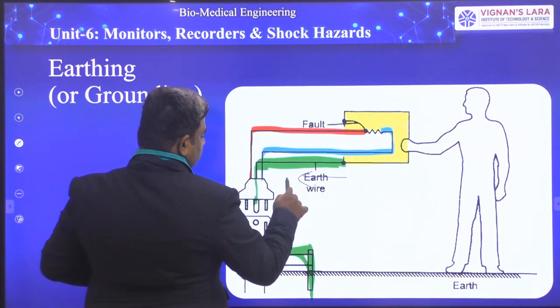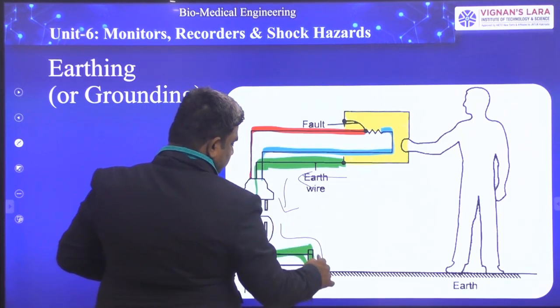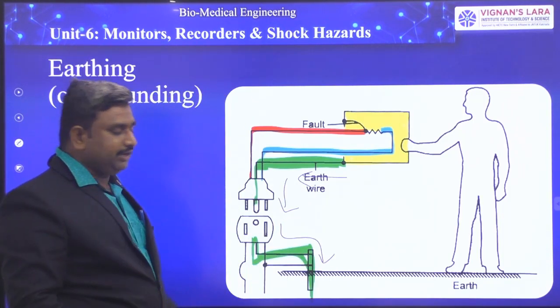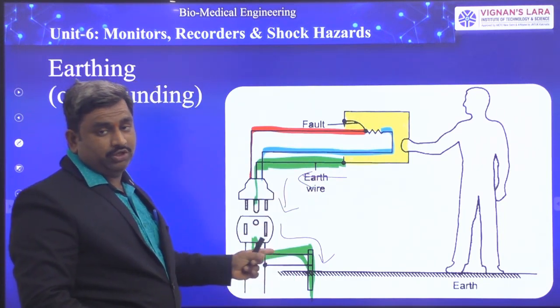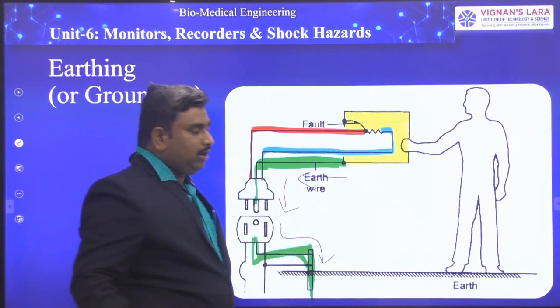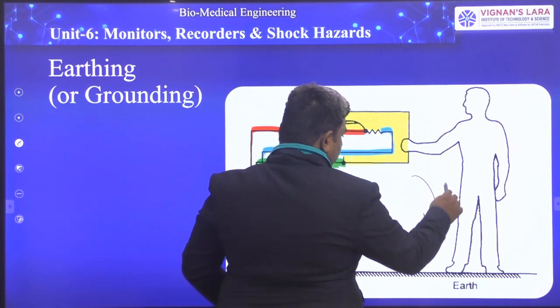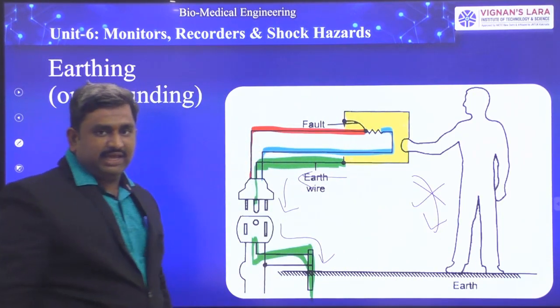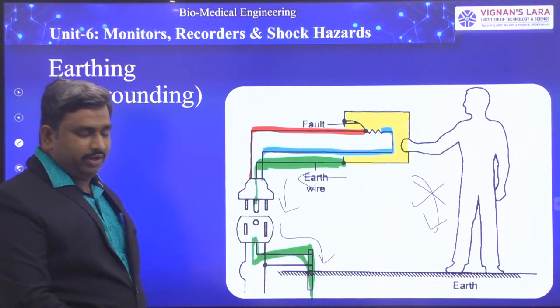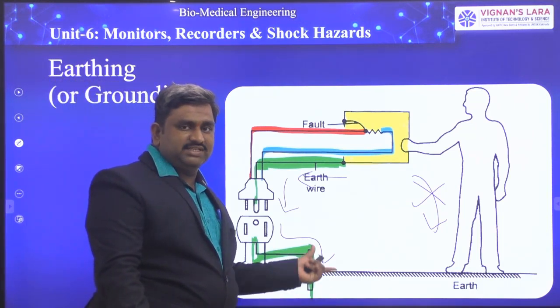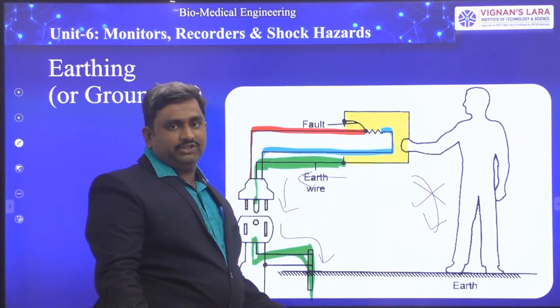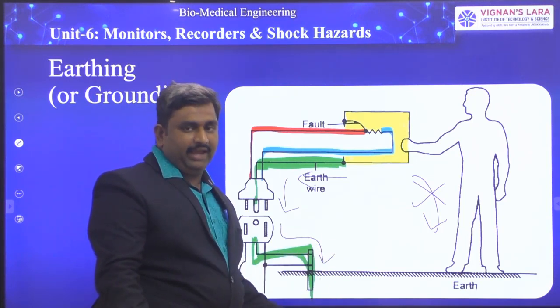The electrical leakage now chooses this path to discharge to the ground. Now there is no chance of these electrical leakages passing to the human body. So if the complete outer box is connected to proper grounding connections with a separate line, other than the phase and neutral,